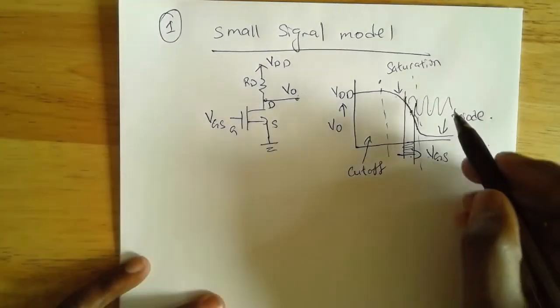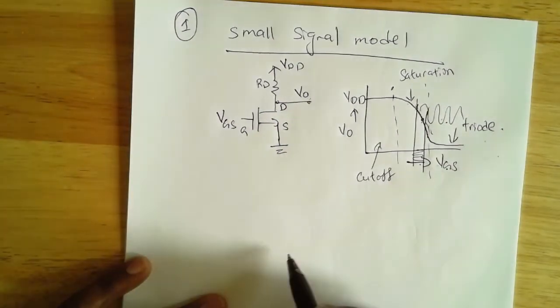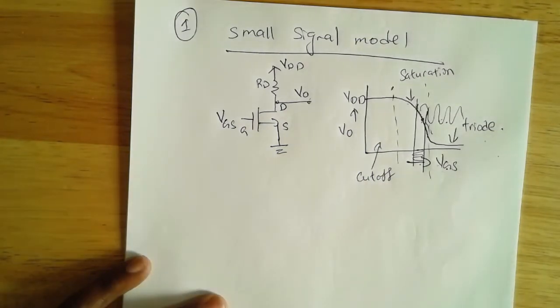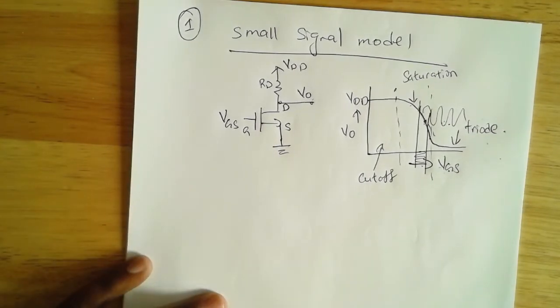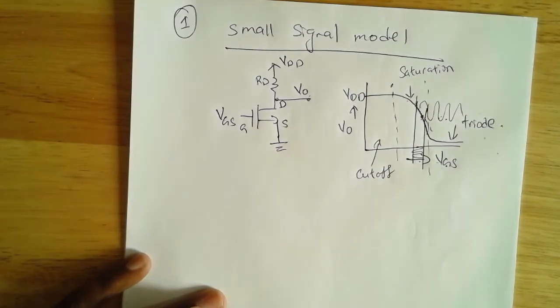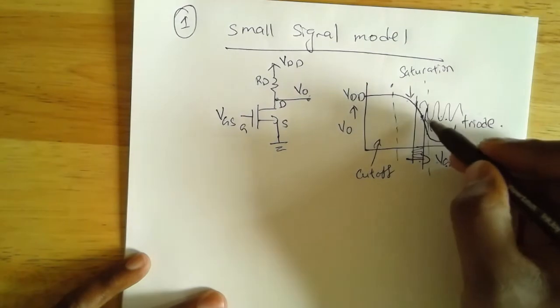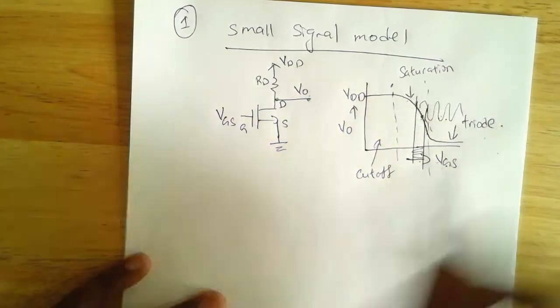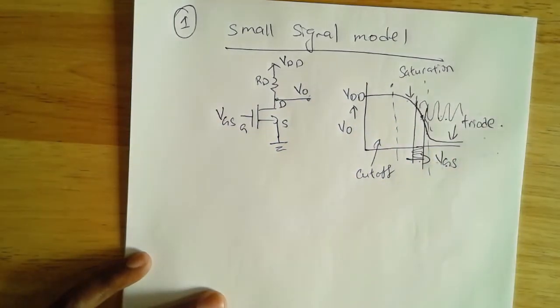If you're only looking at the changes in the output, that will be our AC output, which is an amplified version of my input. So that was our basic philosophy of making amplifiers with transistors, basically by approximating this curve around a point as a straight line. And how good our approximation is dictates how linear our amplification is.